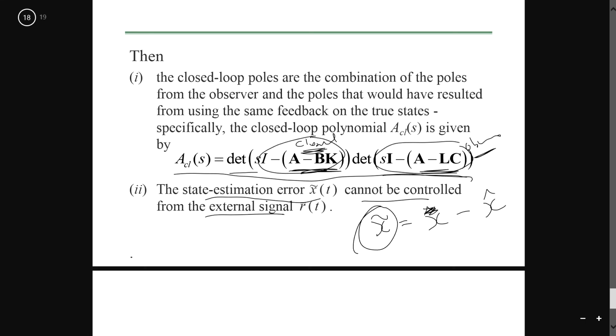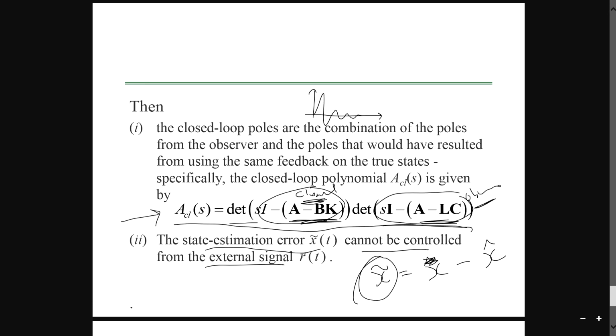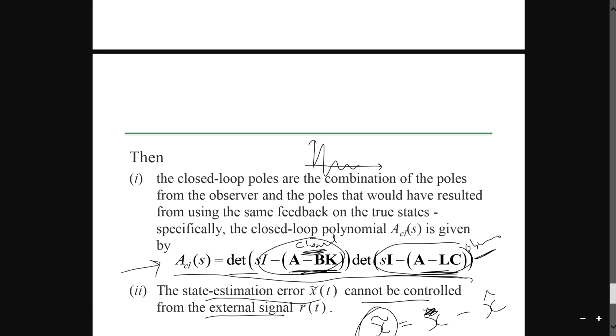If you want to determine your stability, then you'll use this to find your poles. Your poles will tell you the responses. Once you get the eigenvalues, then you'll know how the responses will behave. Is it fast, is it slow, things like that, which we have also discussed in previous videos talking about the roots. Normally we want it to be minus 300 or minus 100, or anything that is negative, because negative is in the left half plane of the S domain.